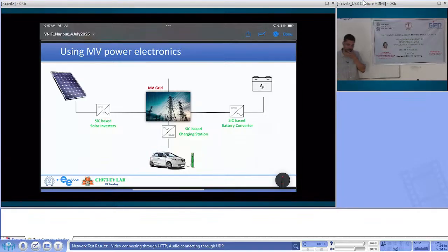I thought so. Yeah, very close answer is what I also felt, that I don't think technically there is much of a challenge, right? Technically, yes, DC, as there is a lot of literature available, in general DC distribution system may be more efficient, but the problem is cost, because AC distribution system is already set up with huge investment over a huge period of time. To do a DC infrastructure or DC distribution system established as a parallel structure with large capability would require a lot of money.